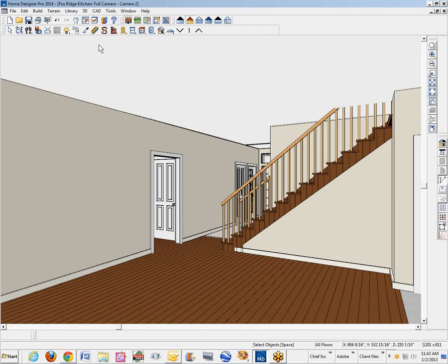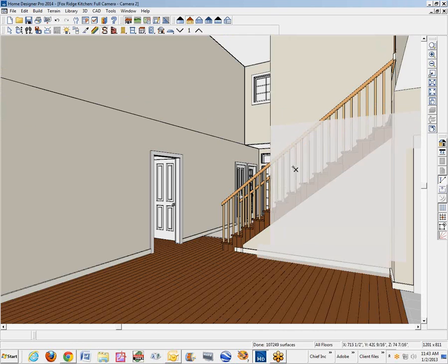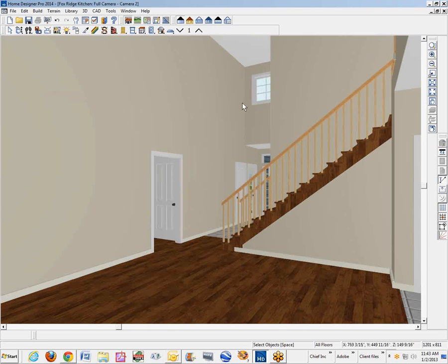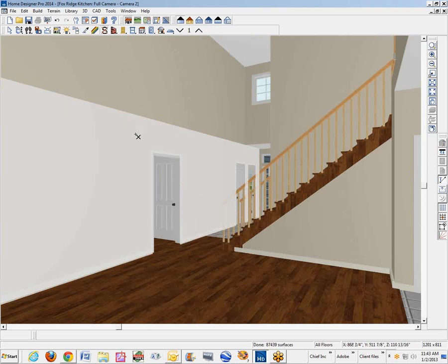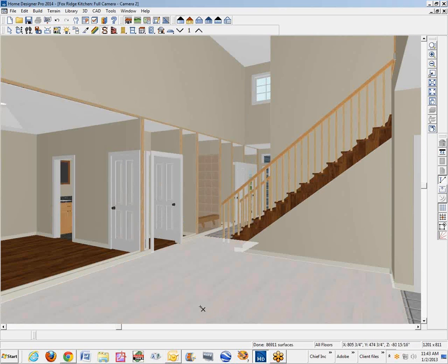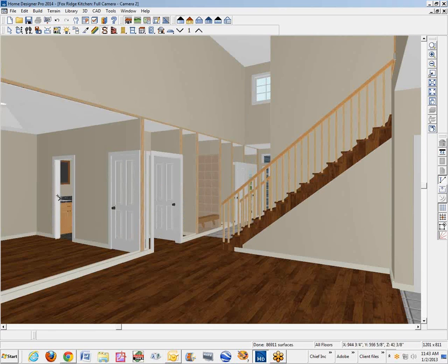and it's still there. You can use this tool here temporarily, delete surface. It doesn't delete it from the model, it just deletes it out of the camera view, and that's what he wanted. Switch back over to render camera. So this is the condition we want to end up with, but this is only a temporary solution, this delete surface thing. It's handy for like getting rid of 3D surfaces temporarily for various purposes.